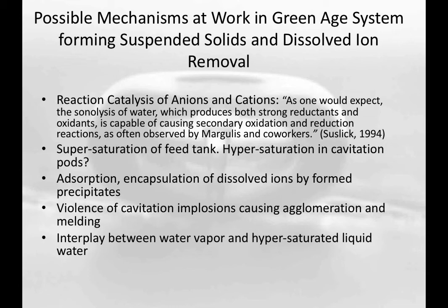So if you were to concentrate your materials in the feed tank by 10 times, and then take that 10 times water and run it through a cavitation system. Now the cavitation system is blowing your water up. So the question is, how much liquid water is actually still in that cavitation pod? Because your gases aren't holding the chemicals or the materials. Whatever constituents have been concentrated 10 times in your feed tank, now as you blow the water apart, let's just say you have 5 to 20% that's still liquid water in your cavitation pod. Let's just go with 10% for easy math.